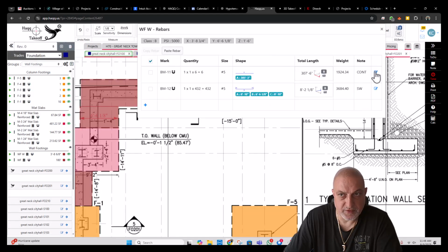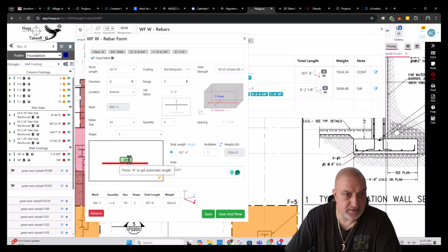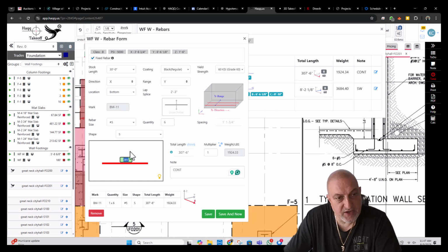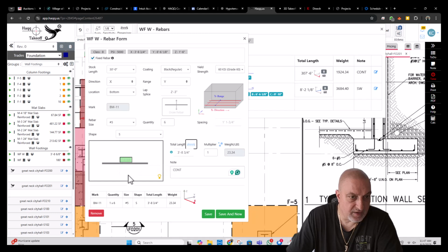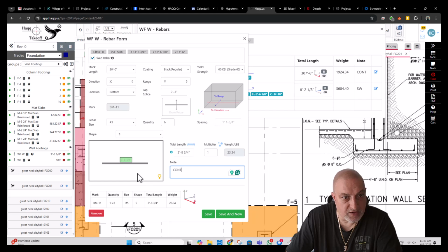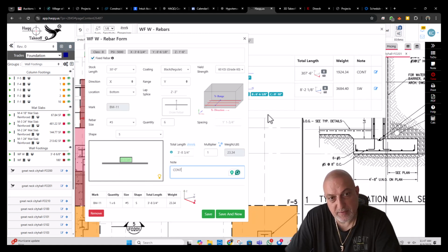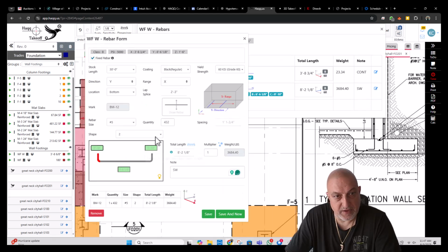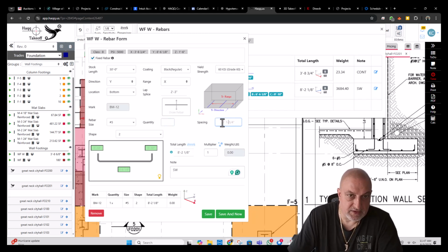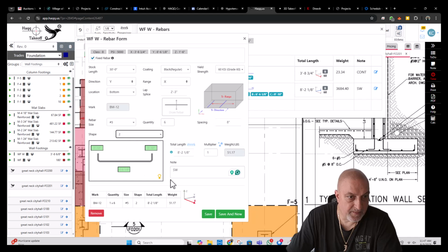You have to be careful what you're doing here. Continuous footings. This one, see, since we changed this element when we're copying, if we didn't change it, it would calculate automatically. But right now we changed it, so it's not gonna calculate. You need to put automatic value A. So when you put the automatic value A and copy to another element, it calculates the new element's length. So here we gotta change. See this? We gotta do not here. Sorry. This is gonna be 8-inch, and that's it.